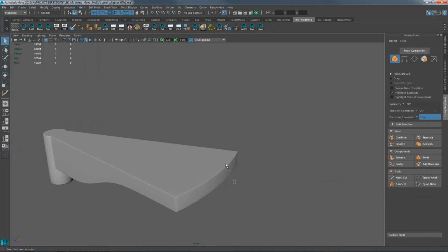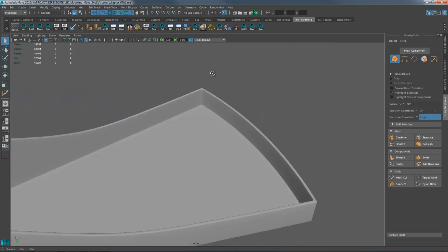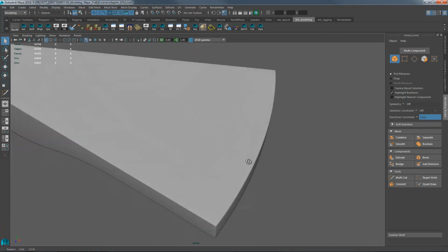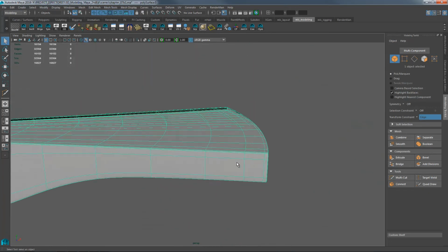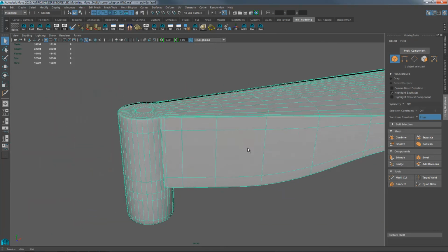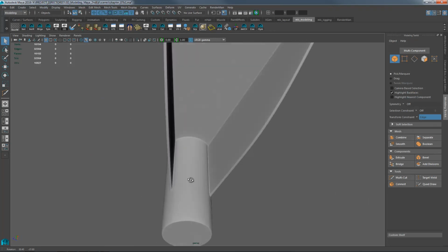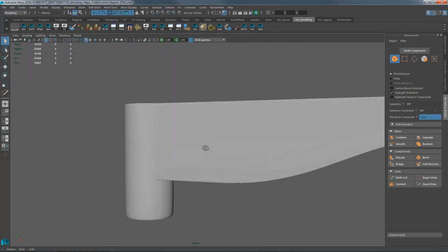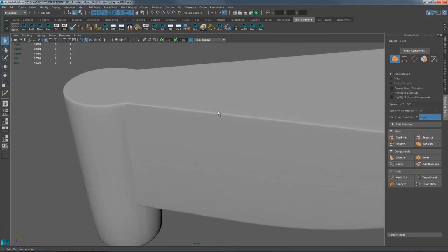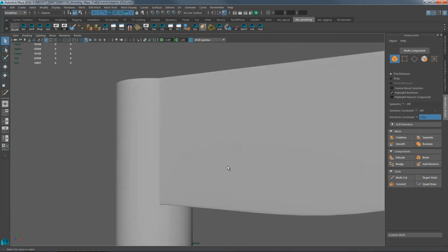So as expected, the outside corners look really good, even with subdivision surfaces. It looks really good and clean out here. I don't intend to use sub-Ds with this setup. I'm beveling the edges so that I don't have to use sub-Ds. But the option is there to use subdivision surfaces. I just have some 6-edge poles to clean up on tops and bottoms at the connections, and that's it.